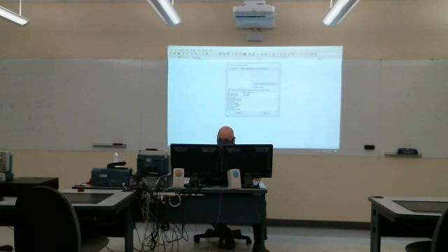Okay, let's see. Op-amps. There's this UE op-amp. Now, you actually have several different models here. The default is a 741, but if I click on it here and choose simple, let me start here. The simple is the one that's closest to the ideal op-amp. And for the simple one, you don't even have to hook up the DC power supplies. For the 741, you do. This is kind of a theoretical model.